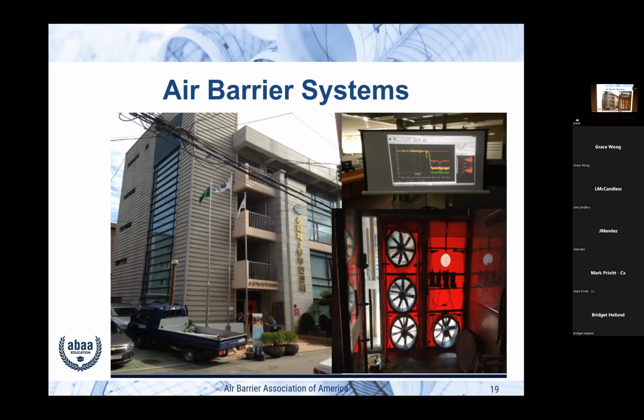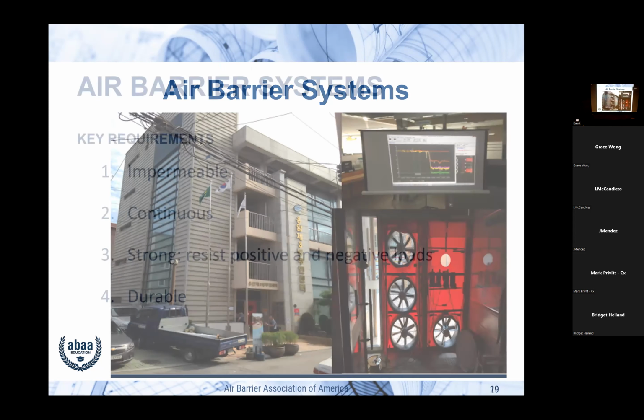They suggested a number of years ago that we combine them because we want to know how much the building leaks. The downside to that is the air barrier contractor has nothing to do with the mechanical system. He can't go make sure the louvers are installed properly, installed the right way, not backwards, how good the ceiling is. He doesn't get paid for that. So the idea of a building air barrier or envelope only test is just to deal with the fabric of the building. But it's a good way to get the information out and get people to understand how easy it is.